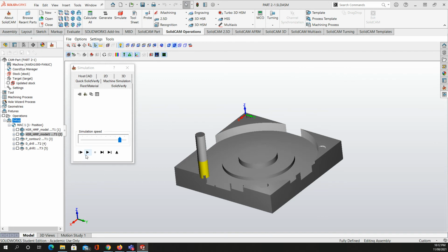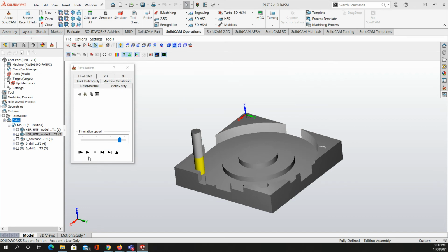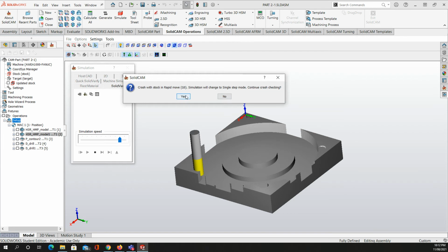So one of the solutions we can do with this one is to drill the holes here at the beginning of any operation, hold the part using the screw, do the profile cutting first, then you come later to do the cuts for the extra work. That's annoying.